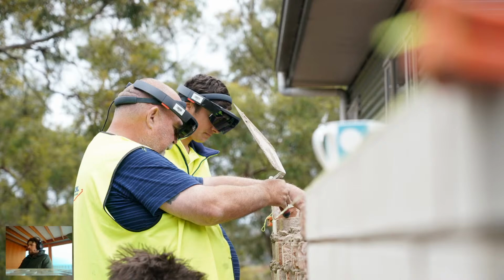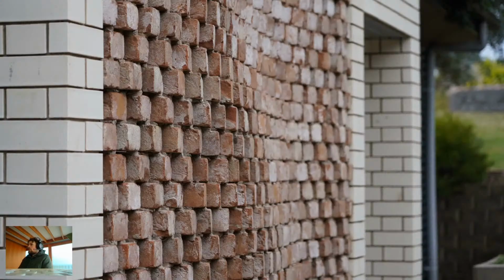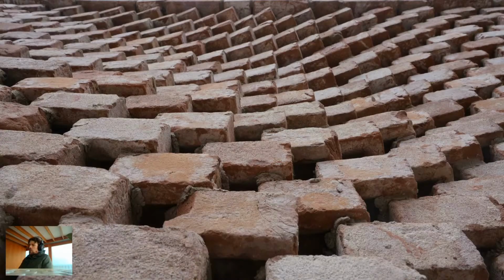And we've gradually been scaling up this technology and finding partners within industry who are willing to give this a go on real construction sites. So we did a small project, a feature wall, about a year and a half ago now, of 600 bricks. And much like with the chair that I showed earlier, if it was to be built entirely conventionally by essentially measuring out where each brick would need to go in the wall, this would take about 2 weeks of construction time. And instead, using a holographic model, we bring that down to about a day of construction time. So these sorts of projects become quite feasible.